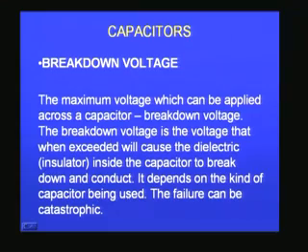Just as resistors are characterized by a value and the power rating, what wattage they can withstand, similarly capacitors are characterized by the capacitance in terms of farads or microfarads, and also another important characteristic, which is the maximum voltage that I can apply to the capacitor without breaking it down. If I keep on applying voltage and exceed a threshold, then the dielectric will break down, making a very large current flow through it, and that is what is called breakdown voltage.